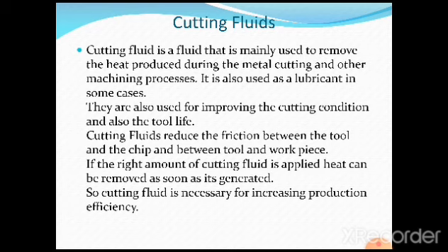Let us go to the exact definition as you are going to see on the screen now. Cutting fluid is a fluid that is mainly used to remove the heat produced during metal cutting and other machining processes. The main purpose of using cutting fluid is to take away the heat generated. There is a pumping system in a machine tool, and there is a continuous flow of cutting fluid in the cutting zone, and again it returns after filtration to the sump, where it is cooled and recirculated. This is a continuous process, especially in automatic machines.